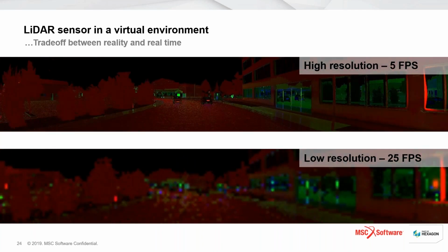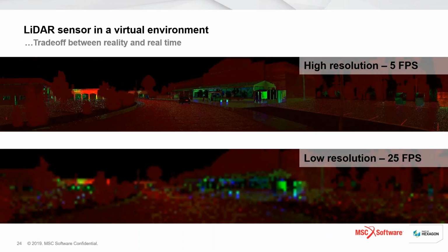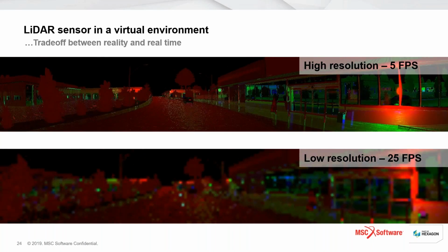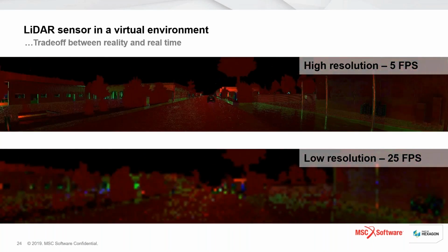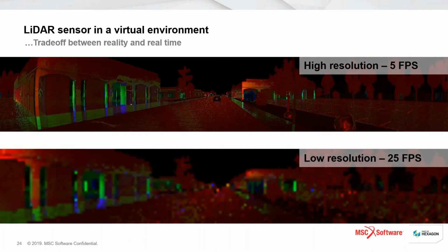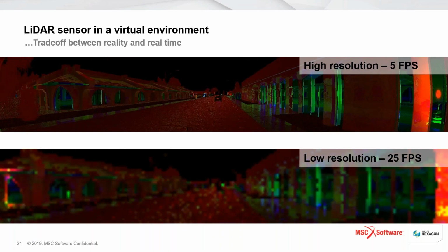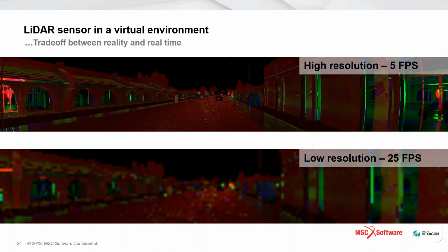We can definitely be in between as well. For the high resolution lidar, it's a definition of 1800 times 300 rays with 4 rays widening per pixel, and we are able to provide this image with a frequency of 5 frames per second.